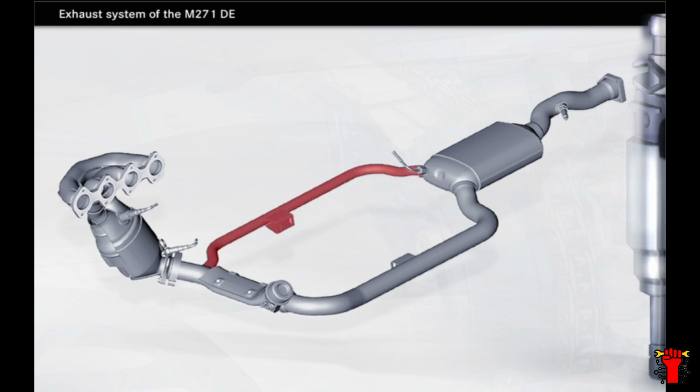The exhaust tract divides up into one thin exhaust pipe and one thick, longer exhaust pipe. The control system can shut off or open this second pipe with the aid of the exhaust flap. Both pipes lead to the NOx storage catalytic converter, where a temperature sensor measures the temperature of the exhaust gas flowing into the storage catalytic converter, and a nitrogen oxide sensor measures the amount of nitrogen oxide flowing out of the storage catalytic converter.